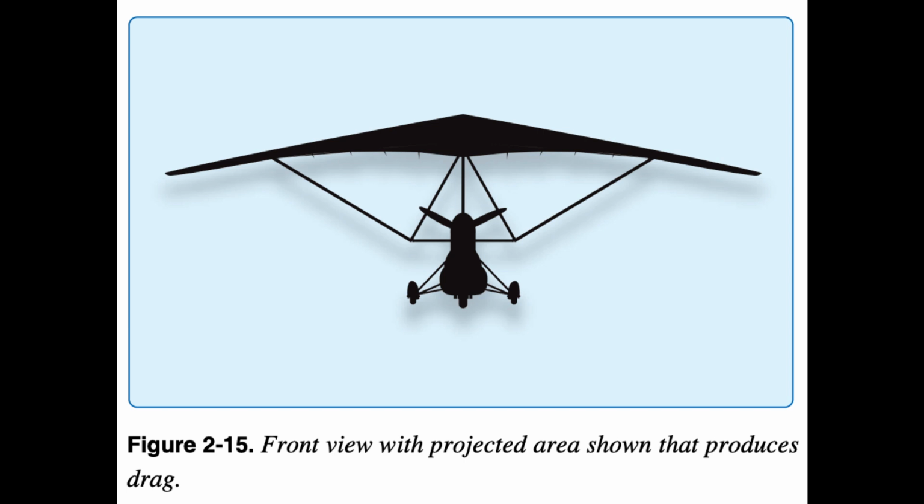Induced drag is the result of lift, and its amount varies as discussed above for lift. Induced drag creates organized circular vortices off the wingtips that generally track down and out from each wingtip. Refer to the Pilot's Handbook of Aeronautical Knowledge for additional discussion on wingtip vortices formation. These wingtip vortex formations are typical for all aircraft that use wings, including WSC, PPC, helicopters, sailplanes, and all fixed-wing airplanes.